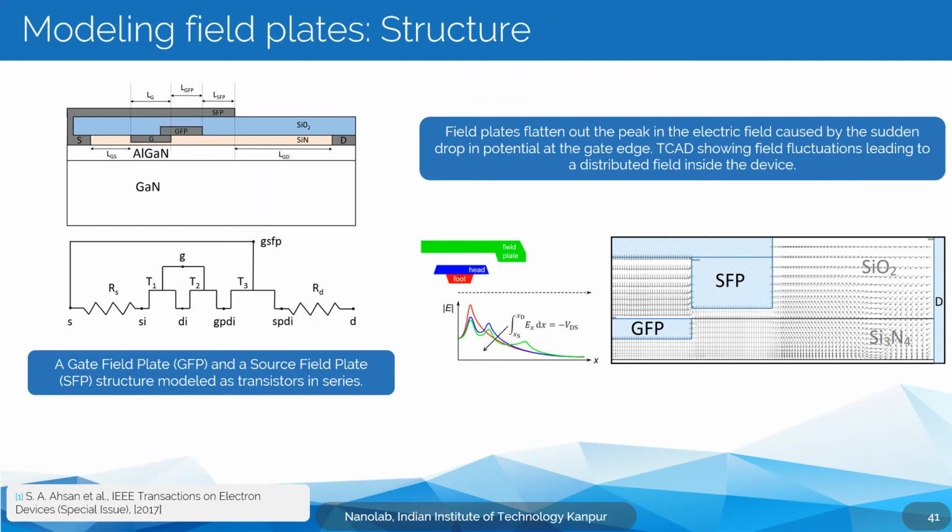Now this next section is a key differentiator of power electronic devices. These structures are called field plates, and the reason they are used is because these devices operate at very high voltages. If we go by state of the art, they can even go up to 600 or maybe even 1200 volts.